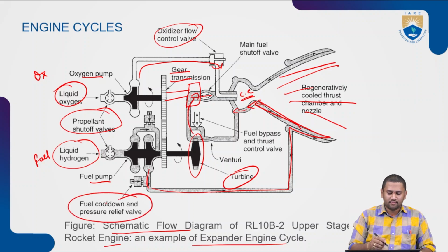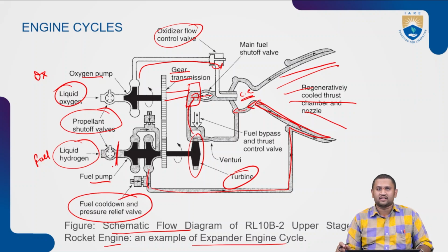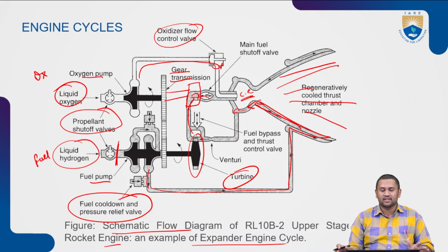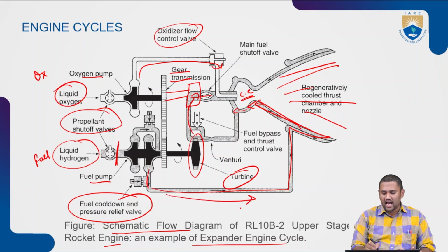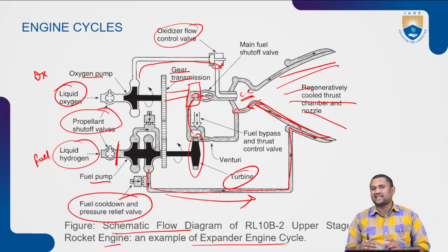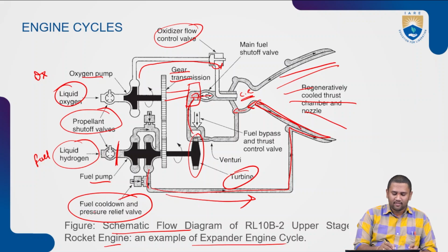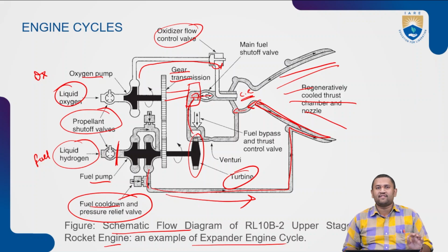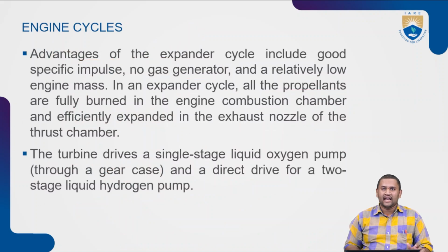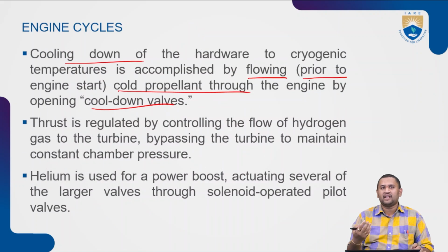Right? What do they do? Basically, till here, everything will be under cryogenics, right? Inside the tank or near to the tank. What about this? As soon as the temperature drops drastically, they tend to condense. So in order to avoid that particular type of condensation, what will we do? We try to flush the liquid hydrogen through the channels it's supposed to flow through prior to the start, so that any mishap can be averted.